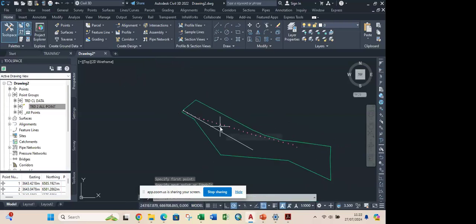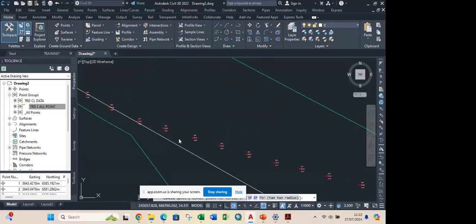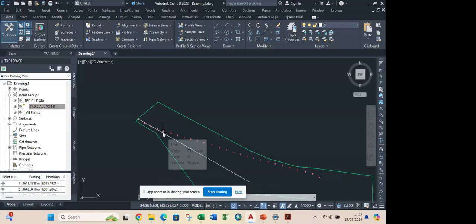Once you see the route, the path the surveyor followed, you'll be able to identify where you have curves on that road. So when starting the alignment, you can also pick your cycle and highlight those locations where you have the proposed curves, based on how the road is undulating, from the topographical survey data the surveyor picked on site.